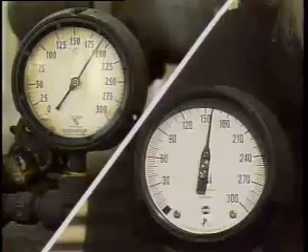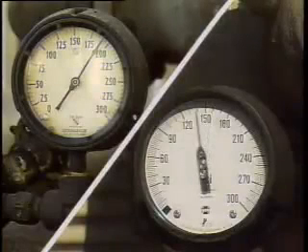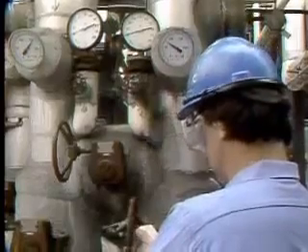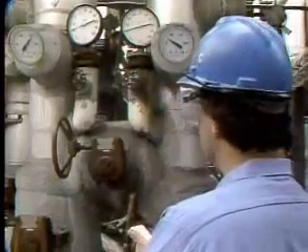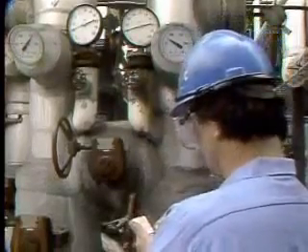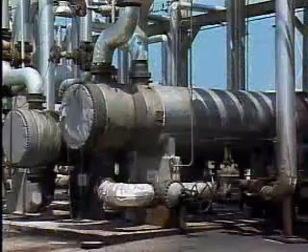organisms inside a unit. In some situations, fouling can become bad enough to restrict the fluid flow. This problem may show up on the heat exchanger's instruments as an increase in the pressure drop or as a gradual decrease in the flow through the affected side of the unit. Fouling may also affect the temperature of both fluids passing through the heat exchanger. When fluid flow is restricted, the heat exchanger must be cleaned.